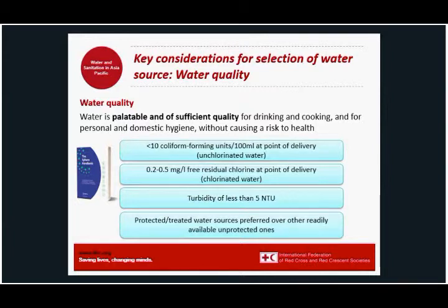We are not always in the position to do a full range of water quality testing and monitoring, but we can undertake rapid sanitary surveys and implement basic water safety plans as risk management tools. Guidance on both these tools can be found in the WHO drinking water guidelines, and we'll provide some links in the resources on the website for this week. But remember, all surface water will be contaminated, and if surface water is being used as the source, it should be treated, including disinfection.